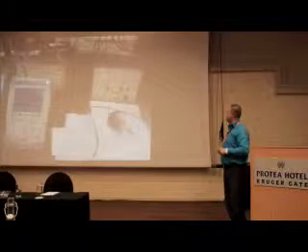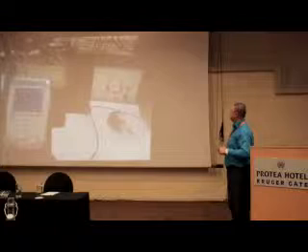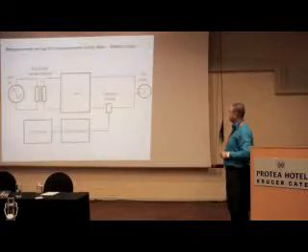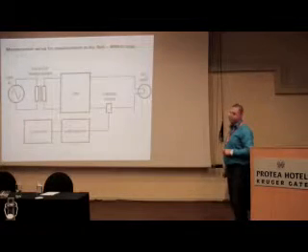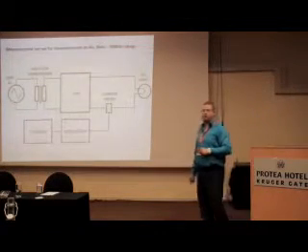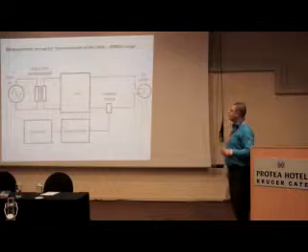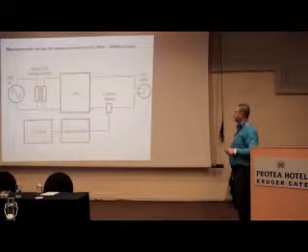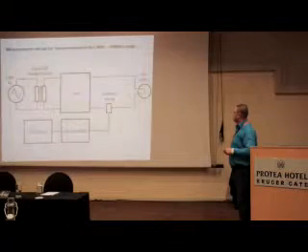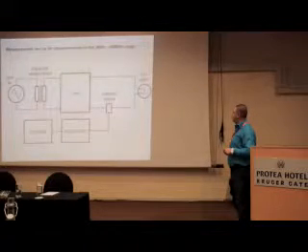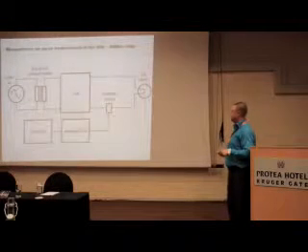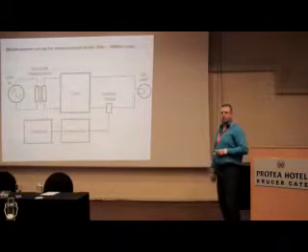This is just to show you the setup. This is the LISN itself. This is the current probe, and this is the spectrum analyzer. As they say, one picture is worth 1,000 words. This is how the connection is made from the 220 volts through the transformer to the LISN, and then to the CFL lamp through a current probe to an oscilloscope or a spectrum analyzer, and then to a computer to process the image itself.